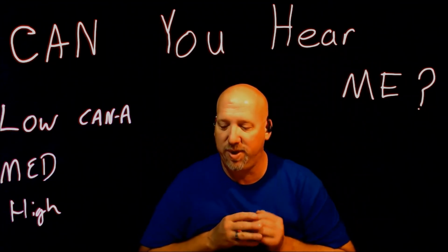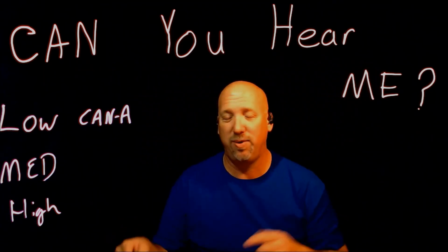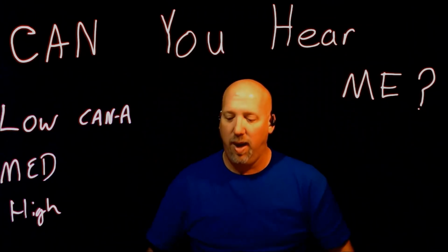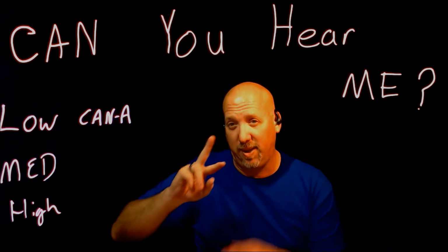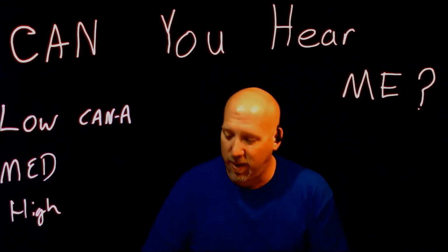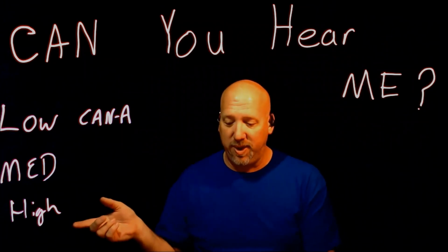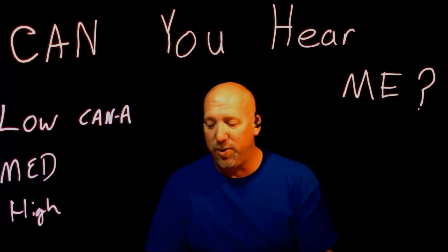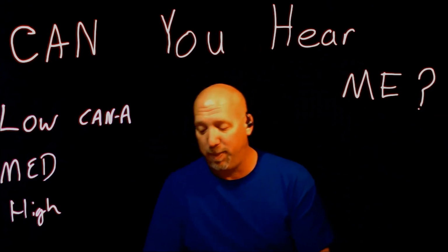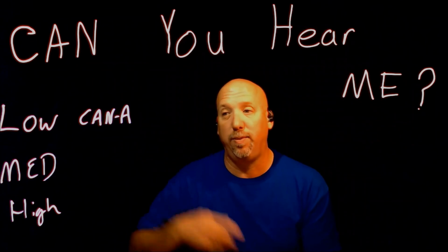This is often used for simple sharing between simple computers like door control modules, door control modules talking back and forth. CAN A is a single wire network, not like CAN B and CAN C, the dual wire networks. It's rarely connected to the DLC. If you're getting any information from modules on a CAN A network, it's being translated through the gateway to a higher speed protocol. Not always, but usually, and that's going to be your CAN C.